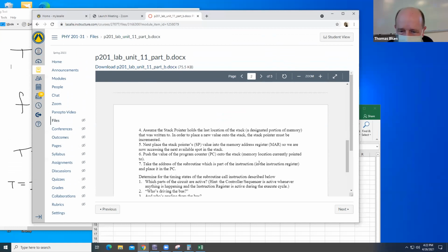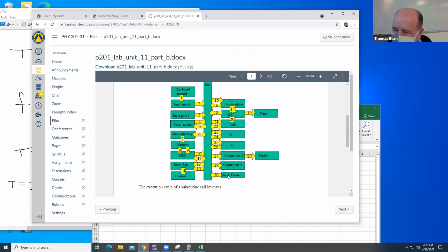And there are 2 things. This is about using a stack and going to a subroutine. There's going to the subroutine and there's coming back. And in the picture, I added a new box because I needed a stack pointer to have a stack. So the old picture is mostly the same, and then I added a new piece called the stack pointer down here. So that is that mapping out of those states. We'll see if anybody asks me about that, say on Wednesday.